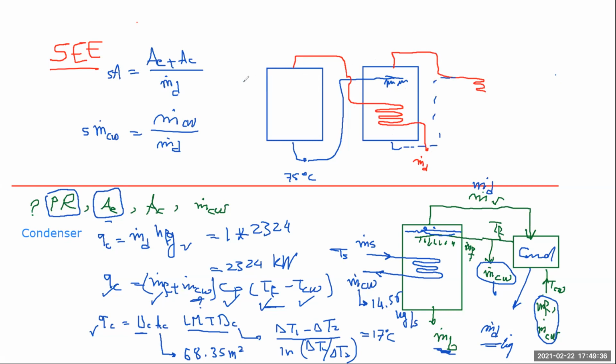So basically, you used external steam for the first effect only. After that, your own vapor is the source of heat for the next effect, so that you can have additional vapor, and the next effect, and the next effect, and so on. What I'm talking about here is basically the idea of having the MED, or the multi-effect desalination. So you are reusing the vapor that you have generated, using the energy associated with its condensation to get more water and more water and more water. And that's the basic idea here.